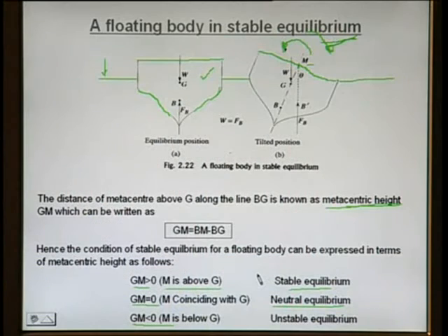Many times these ships are stable, but if we have a very large wind force or very large wave, then this ship may get tilted and it will not regain its original position till some new force is applied through an external crane or other device. And for ships, submarines or boats, this metacentric height is very important when it is in floating condition.